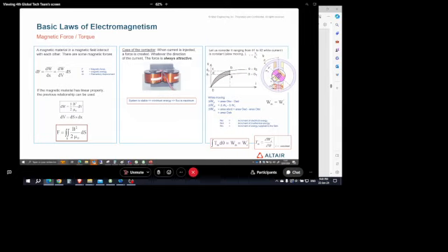So if we take this device, which looks like a salient rotor synchronous machine, and I supply only the rotor and not the stator, then if I move the device, I will create what we call a cogging torque.